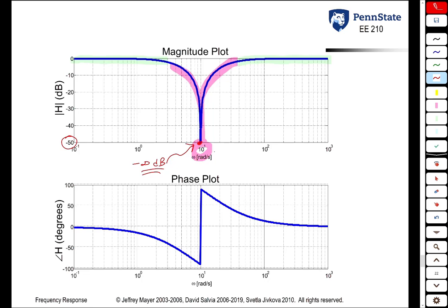And what is this frequency? This frequency is 1 over the square root of LC. So just like in the band pass filter, in this filter called a band stop filter, we see that the value of the capacitor and the inductor dictates the midpoint of the stop band. So this is a pass band on the left. This is another pass band on the right.